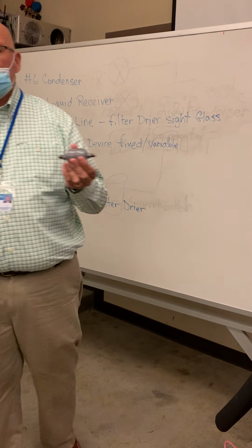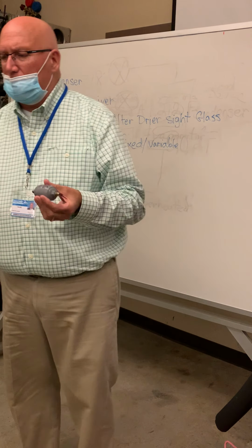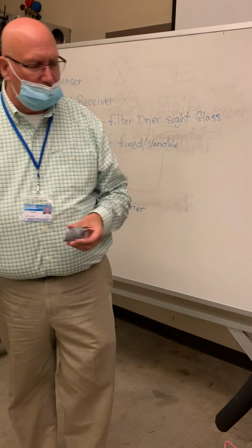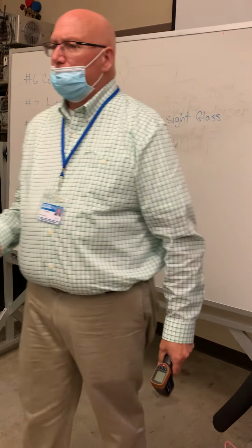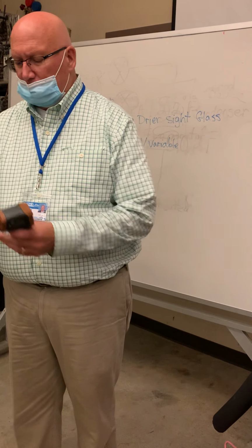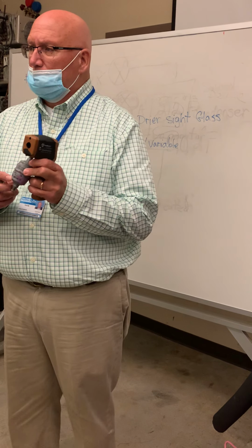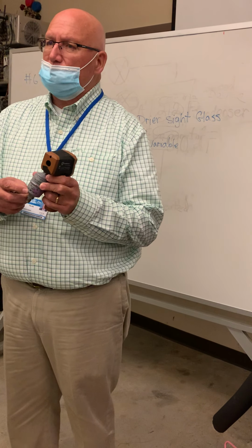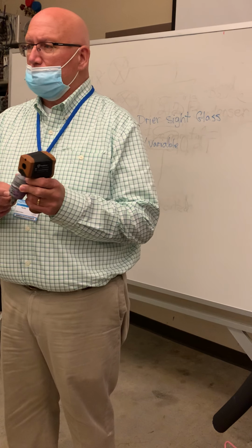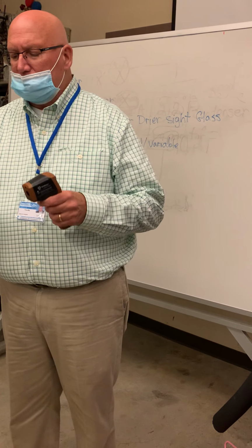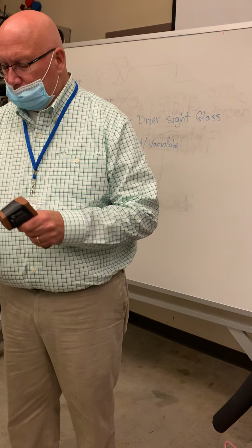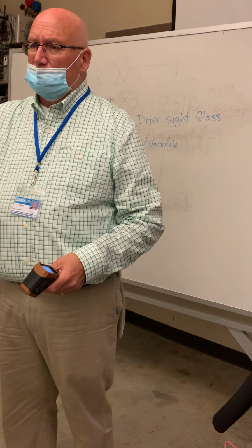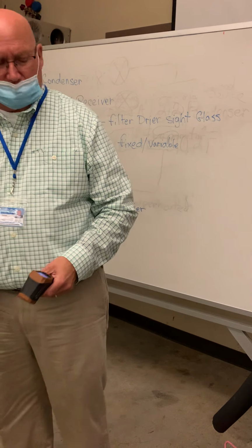So do filter dryers, like all filters, occasionally need to be changed? The answer is yes, absolutely. That's a great point. The way that you tell a liquid line filter dryer needs to be changed, first off, filter dryers have arrows. So when you install this, do make sure you install it going in the right direction because it won't work out for you otherwise. But now there'll be copper lines on either side of this, right? You would shoot it on this side and on this side. And if you get more than a 3 degrees temperature difference, this is clogged. It would need to be changed.